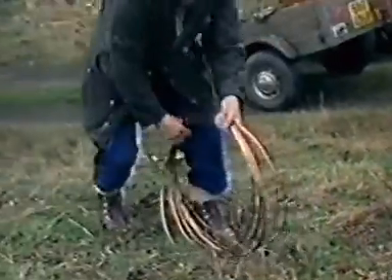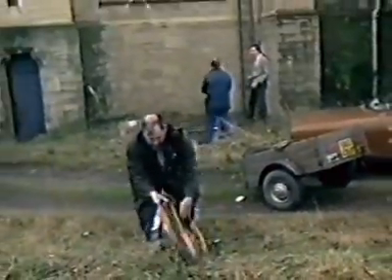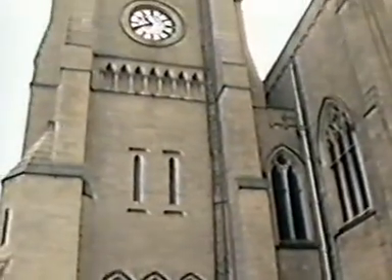The main thing is to get the aerial as far as we can in the center of the area that we want to cover. This church is to be used to suspend a medium-wave aerial for a temporary transmitter for the town of Bury. The aerial is just a copper wire, but its length and the height of the church have been carefully chosen to get the best medium-wave transmission.